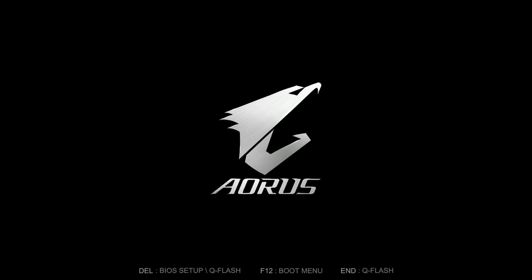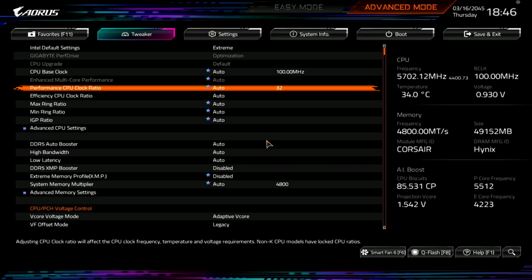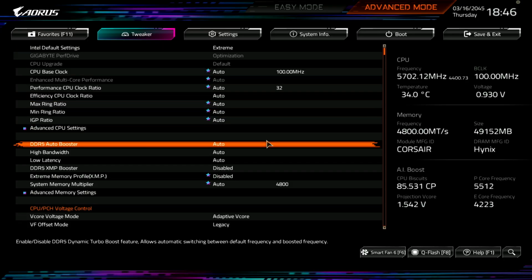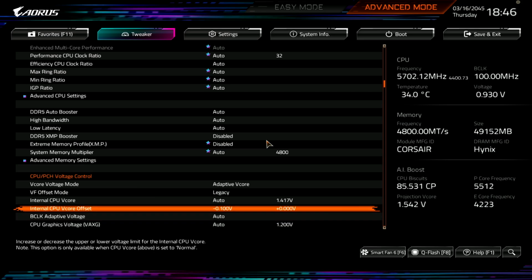Because in Intel's own documentation, that's the maximum load line for the high core count CPUs. Most motherboard manufacturers are, well, not particularly. Actually, I think even Asus has level 3 at 1.1 milliohms and level 1 at 1.7 milliohms, and that's actually more effort than most other vendors will do.